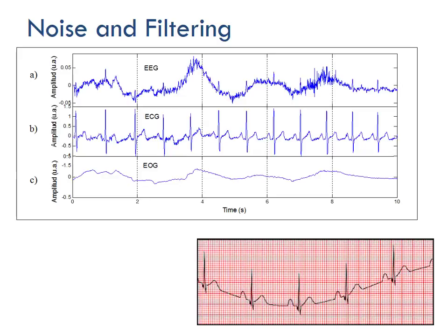In the bottom, in the red there, this is a smooth signal of an ECG. You see that polarization, that top peak there, that's what it should look like. Then you have a peak down, and then a smaller peak up, which is kind of spread out, and then you go back to normal, and then you repeat it. That's what the ECG pattern, the second one down, should look like. But you see there's a whole bunch of other little lines splintered out through there. That's because this ECG probably hasn't been filtered properly. The bottom one has been filtered much better because we get a much smoother curve, and it's easier to see what we're looking for. If you go back to the middle one, all those tiny little ups and downs are a high frequency signal that's added on top of the signal that you want.